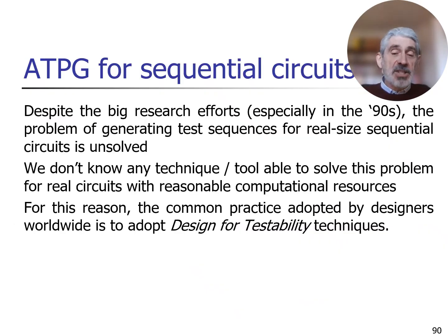Now, the real situation is that despite the big research efforts, especially in the 80s and in the 90s, the problem of devising an algorithm that could be used systematically to generate test sequences for stuck-at faults in sequential circuits was, let's say, unsuccessful. So still at the moment we don't have any real algorithm which is able, for real size sequential circuits, to generate test sequences.